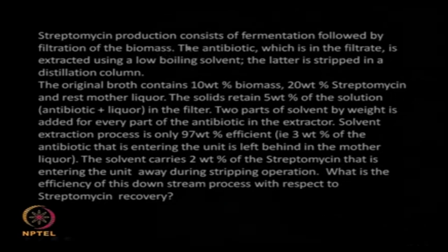After the filtration, what they do is they add a low boiling solvent to extract the antibiotic streptomycin, and then you can use a distillation column to remove the solvent. So the streptomycin will be left at the bottom and the solvent can be recycled and fed into the extractor to once again remove the streptomycin. So this is the entire process. You have a filtration, you have an extraction, you have a distillation.